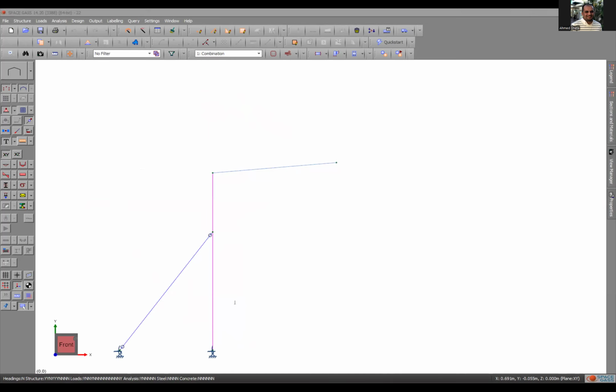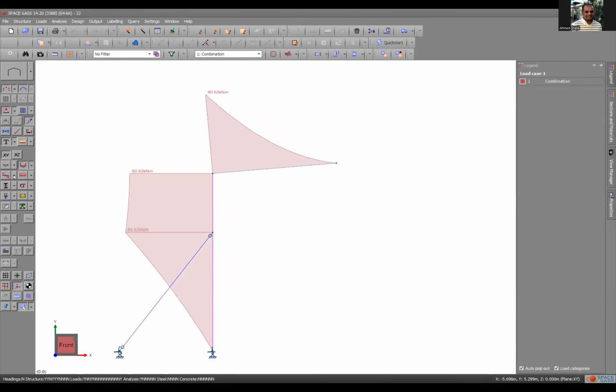So your report will include this calculation for loading, bending moment diagram, shear force diagram, and so on, and attach to it or combine with it the software results from here, moment and deflection and so on. It's better to show one by one, because if you add all the drawings together, it will not be understood.